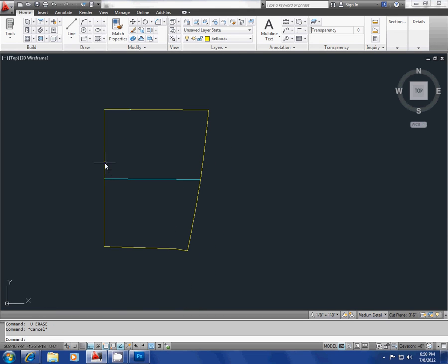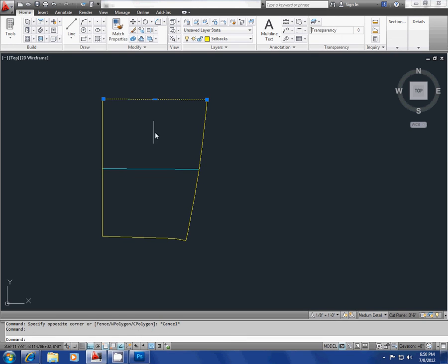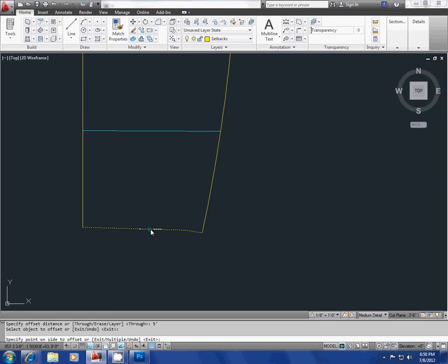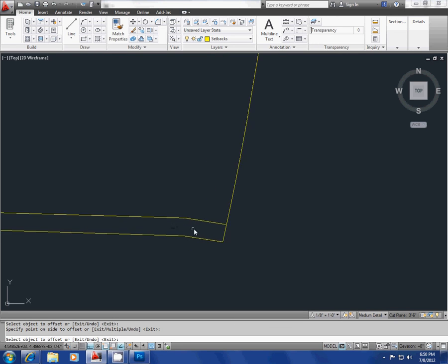Okay, so I know that my front yard or my side yard setbacks are what? 5 feet. Yep. Right. You can also press offset, so you can do offset. Press 5 feet. So O enter. Then it asks you for the dimension, and then it asks you for where you want it to be, right?